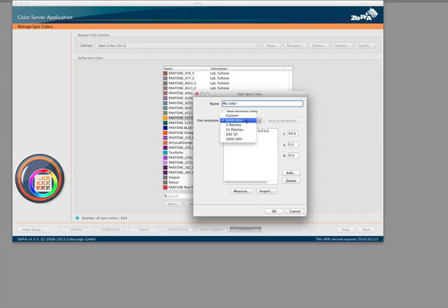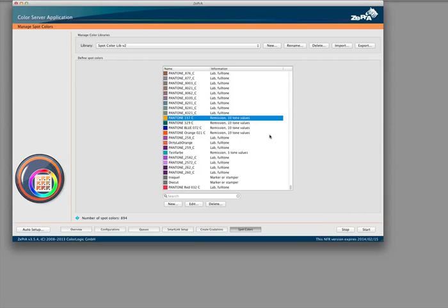For example, you have a spot color gradient with 11 patches in there, including white. So you would select this one. So then you have the list of each of the 10%, including white. And then you simply go to measure, and then you can measure with certain instruments that we're supporting. So that's the demonstration of how to set up a spot color library.